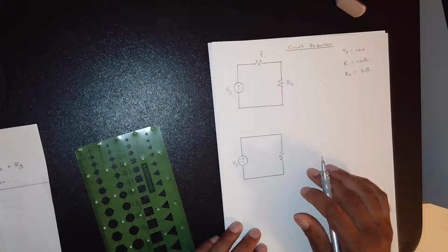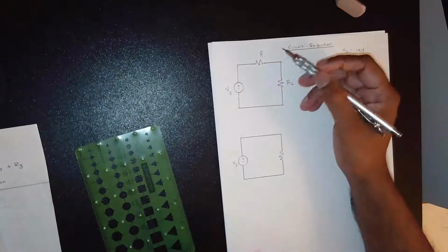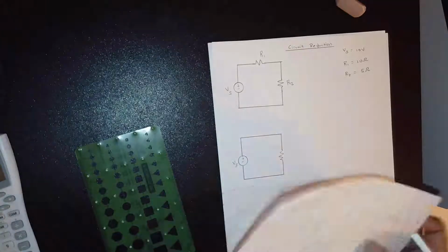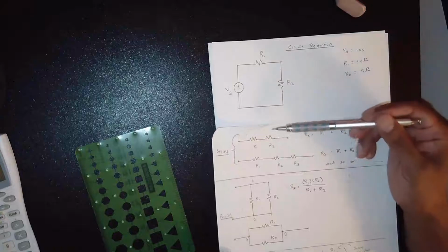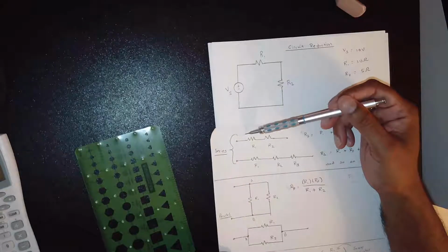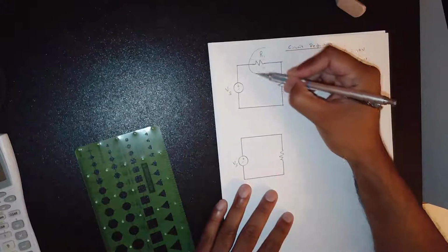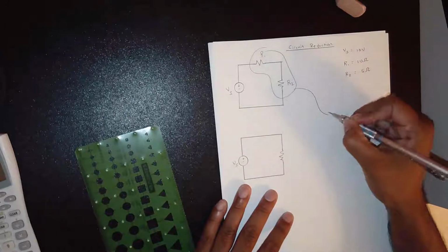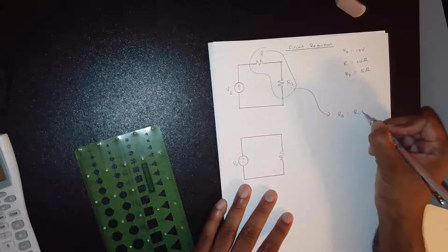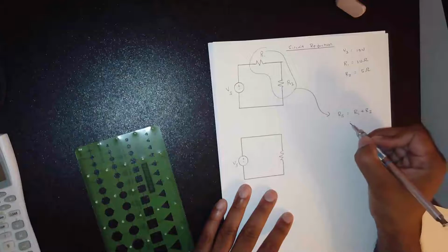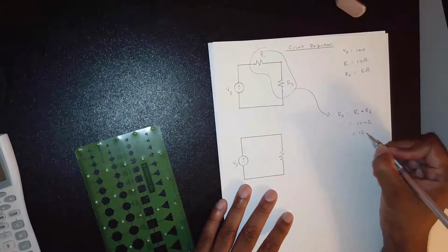Okay, here we have a resistor. Obviously, we're going to reduce it to one resistor. After some practice, we should be able to do this. This, in this circuit, is a series circuit, right? And the series circuit is going to break into two resistors like so. So we're just going to take these two resistors and make them into one resistor. Call this RS, which is equal to R1 plus R2. 10 plus 5 is 15 ohms.